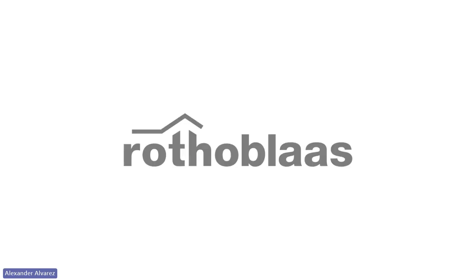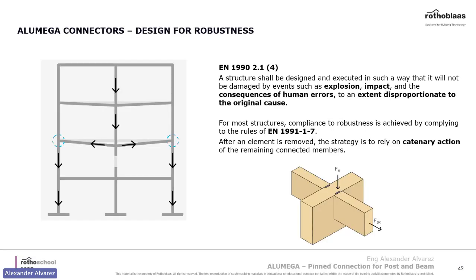and how it happens. Even if it's a shear load, there is some sort of rotation happening right here, especially since these hangers are pin connections. If you pin something, you can still rotate it, but there's a certain amount where you rotate just a lot and it becomes useless. So you want to make sure the capacity is able to handle a small amount of rotation, just enough that it's still able to handle the resistant load.